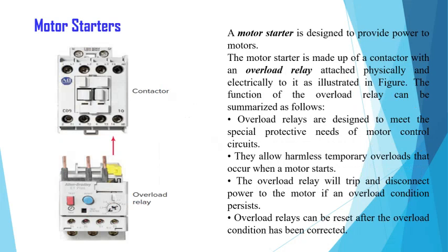Our next field device is the motor starter. A motor starter is designed to provide power to the motors. A motor starter is made up of the contactor, which is used along with the overload relays. These overload relays are attached physically to the contactor and electrically to its control circuit.